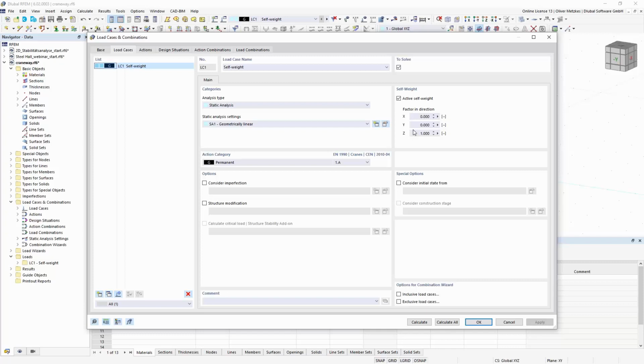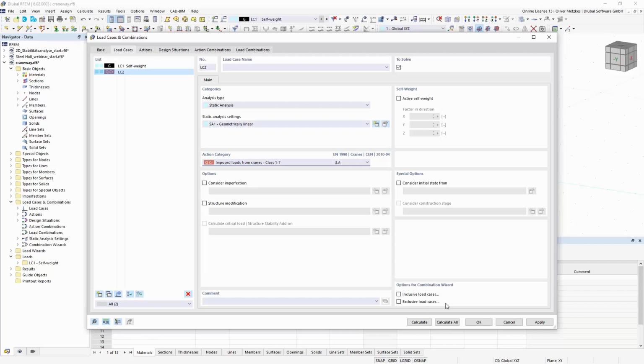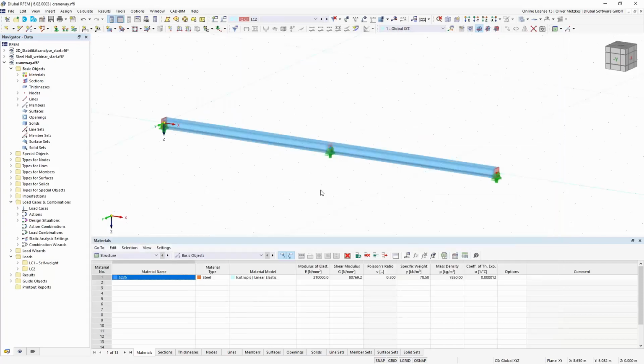So there we always apply the loads in the shear center, but now for warping torsion calculation, this additional torsional moment is important. So now it's really applied in the center of gravity. We have already our self-weight loading, and now I want to also create some crane loading on my beam. And as I have said, we don't have this moving load implemented for now. So I could create it, for example, by hand, and I will just first show it as an example.